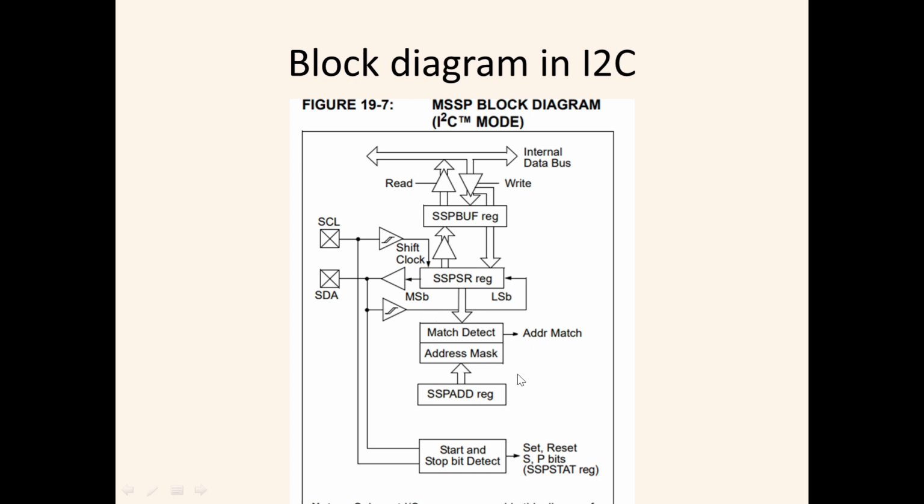Other settings like reset bit, start bit, stop bit are mentioned in the SSPSTAT register, which gets associated with SDA and SCL. So here you can conclude that SSPCON1, SSPCON2, SSPSTAT registers are the control and status registers in I2C mode of operation.